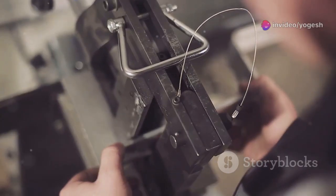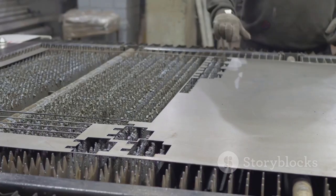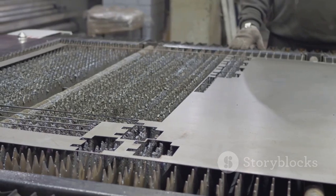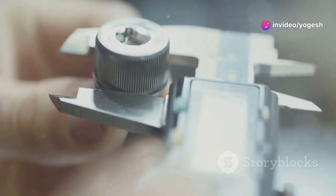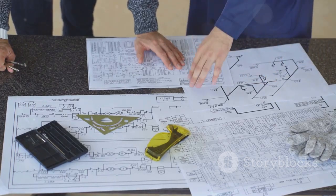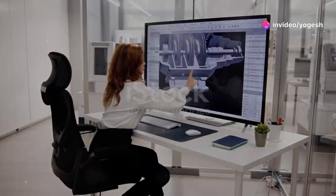For example, a bend that's too tight can crack, and a hole too close to a bend will deform. Good design distributes stress, avoids weak points, and saves money by reducing waste and extra steps. Designing for manufacturability, DFM, means using standard sizes and simple features. Collaborate with your fabricator early and follow these rules for smoother, cheaper production. These guidelines make your designs practical, strong, and cost-effective.